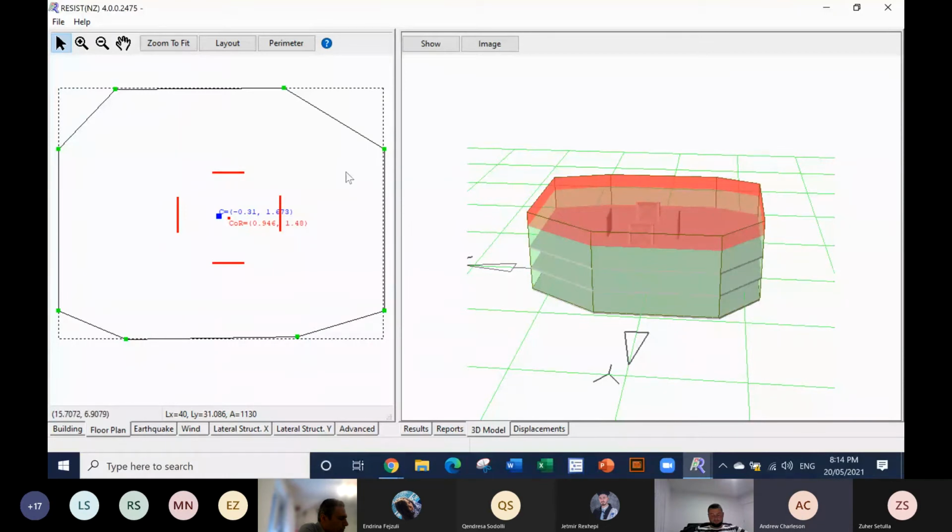And then that means around the perimeter of my building, I can have these slender columns and beams just supporting gravity load. But this building will not perform as well because it will rotate torsionally, and therefore it's likely to suffer greater damage than if the walls were near the perimeter. So yeah, the principle is try and keep your structure nearer the perimeter if you can.